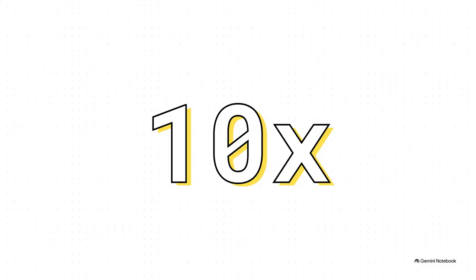And this rule gives us the absolute magic of traditional hydraulics: force multiplication. Just picture a sealed U-shaped tube. If you push down with exactly 1 pound of force on a 1 square inch piston, you create a very specific pressure. Because the fluid won't compress, that exact same pressure travels everywhere. So if your output piston on the other side is, say, 10 square inches, that pressure pushes up on every single one of those inches. Suddenly, your 1 pound of effort is lifting a 10-pound weight. You're trading distance for power, creating this massive mechanical advantage that literally drives modern industry.